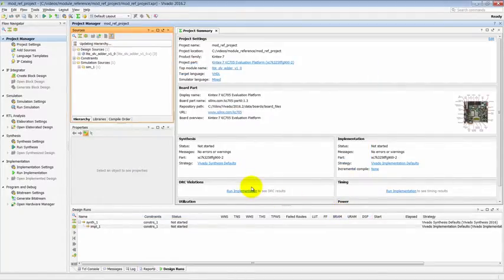One of the things that should be emphasized here is that you should make sure that your RTL code synthesizes and implements properly prior to instantiating the code in the block design. This will prevent unnecessary churn or fixing of design errors. Once the RTL module has been proved to implement successfully, only then should you instantiate the RTL block in the block design. Now let's create a block design and add our RTL source to it.